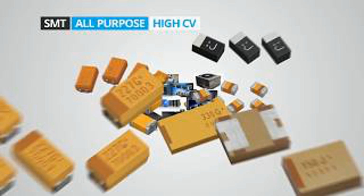5. Capacitance and performance. The capacitance, the ability to store energy, is influenced by the surface area of the tantalum anode and the thickness of the tantalum pentoxide dielectric. Tantalum capacitors are valued for their stable and predictable behavior. They perform well over a wide range of temperatures and frequencies, making them suitable for high-performance applications.